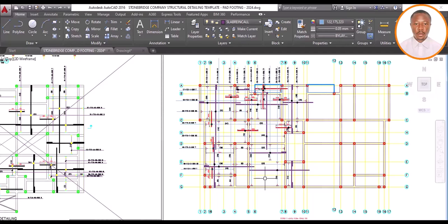Because you deleted one and replaced it, it names it 6. Likewise, if you delete another one, maybe beam 8, and put another one, it's named beam 9. But in a real sense the total beams you have is maybe 6 or 7, and because you don't know how to solve that problem, it might be showing you 8 beams. Likewise, the column arrangement.